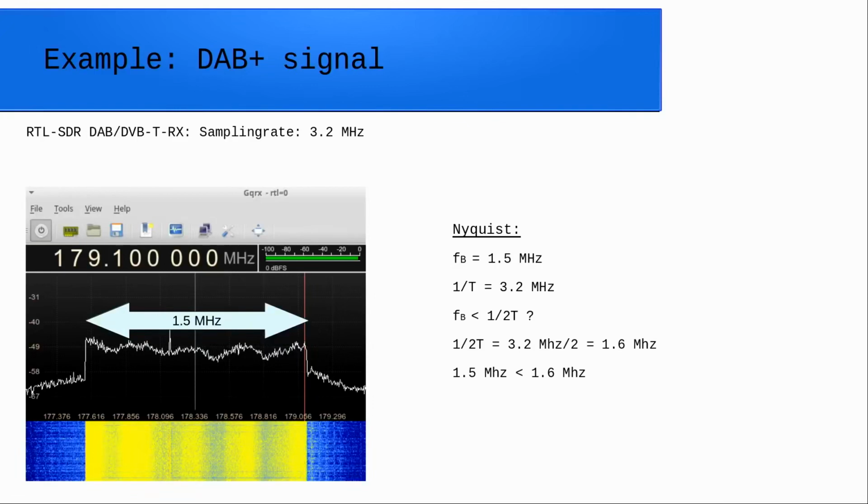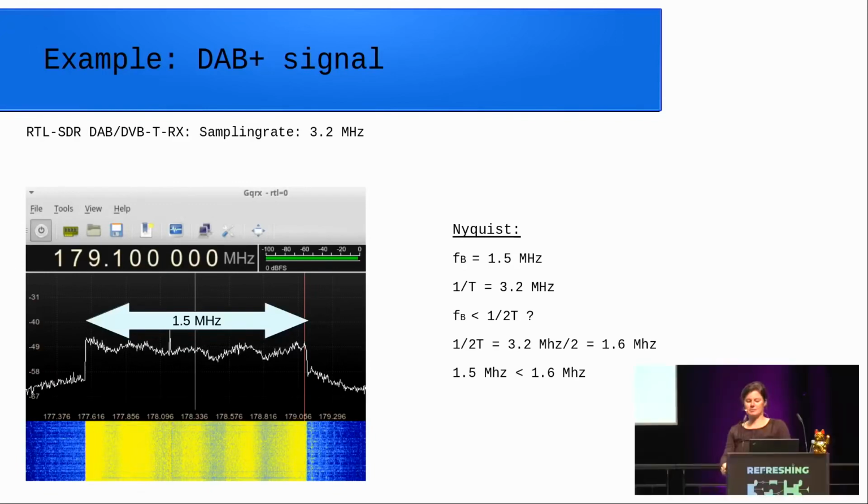So DVB-T here doesn't use the SDR mode of this chipset, but it has a dedicated DVB-T chipset in here. Chipset development is quite expensive, but if there is a mass market, and for television there is a mass market, they can be produced very cheaply. So actually the SDR mode was probably added for the DAB reception.